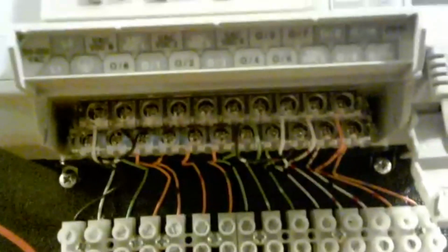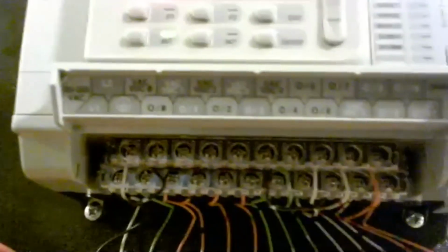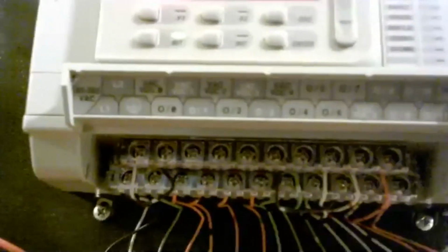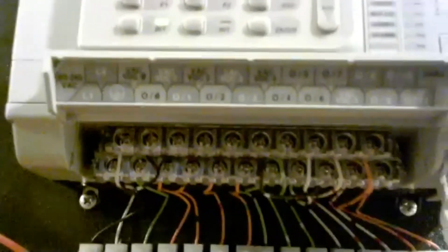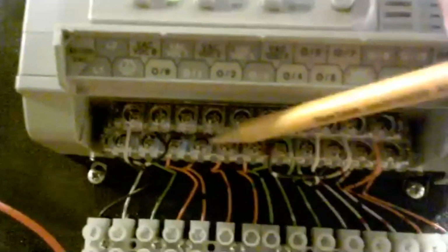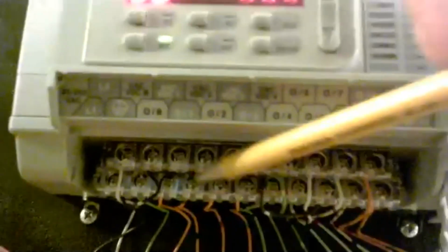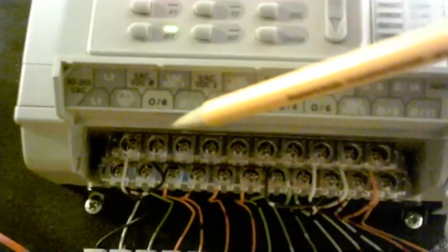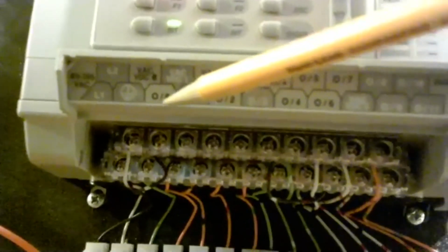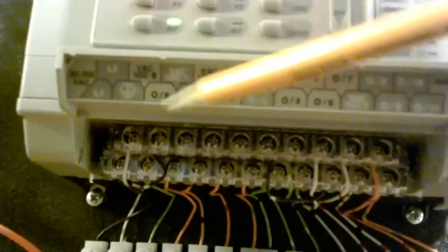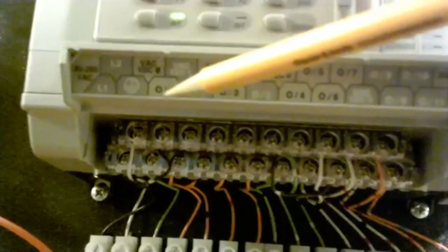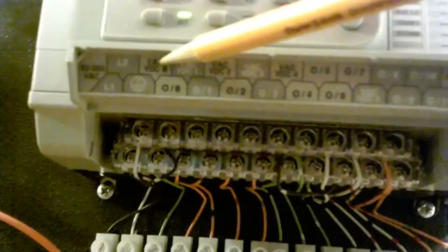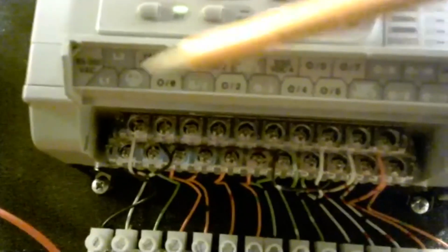And they're already connected up. Those large terminals are connected to the PLC. And also another thing is up top, if you notice above, like here you have output 0. You see that? That's going to be for the first starter. Now that one gets its power from VAC 0. So you got to put 120 volts on that.